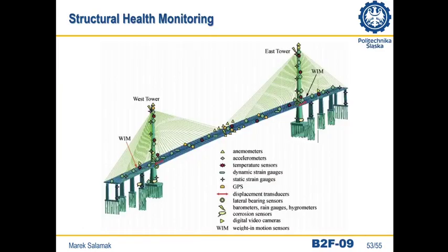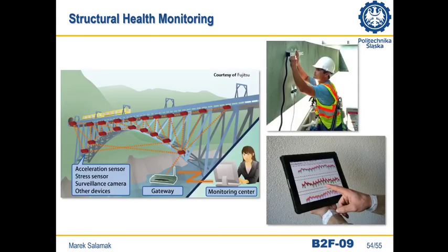Electronic monitoring systems for technical conditions of structure are the most advanced at present. The largest and most responsible bridges have built-in hundreds of sensors that measure various physical quantities such as accelerations, displacements, deformations, temperature, wind loads, etc. They allow real-time observation of the structure's response to external loads. They can also help to identify the damages and make decisions about whether to close or repair the bridge.